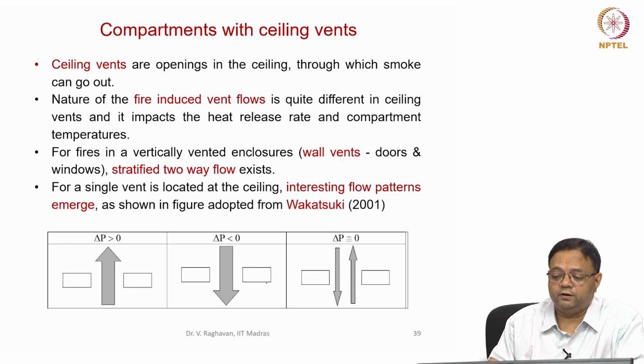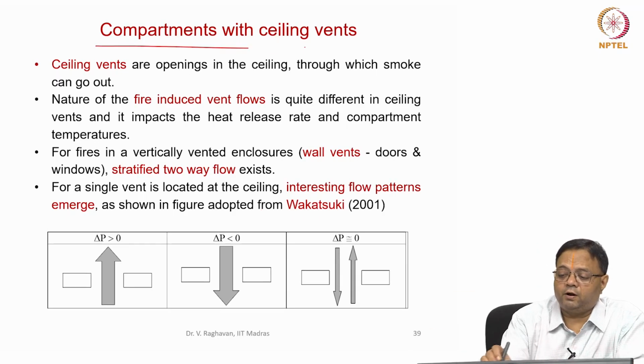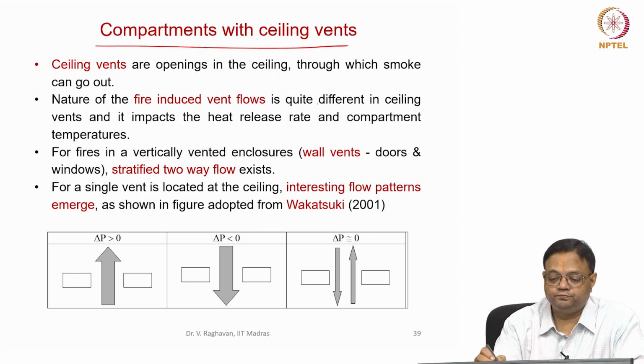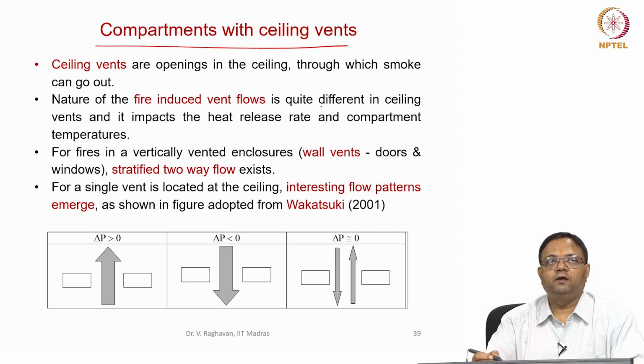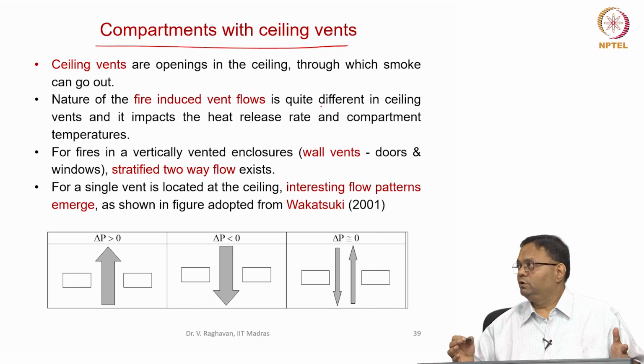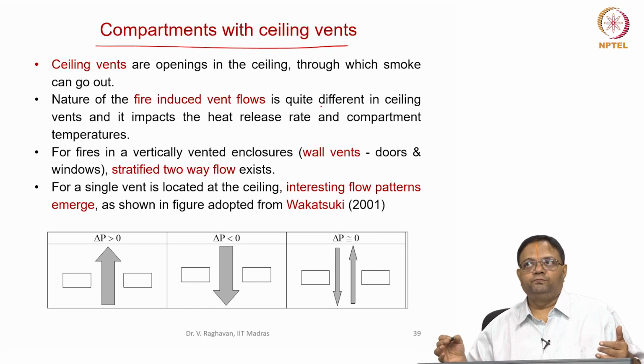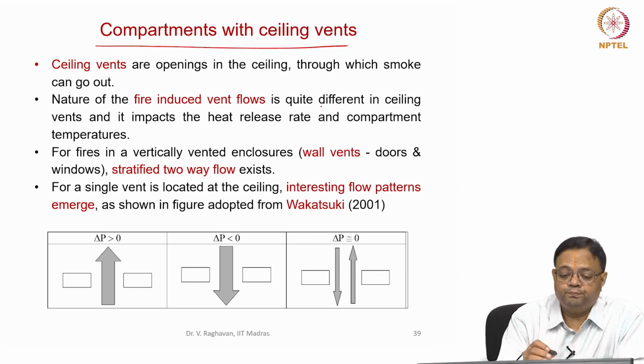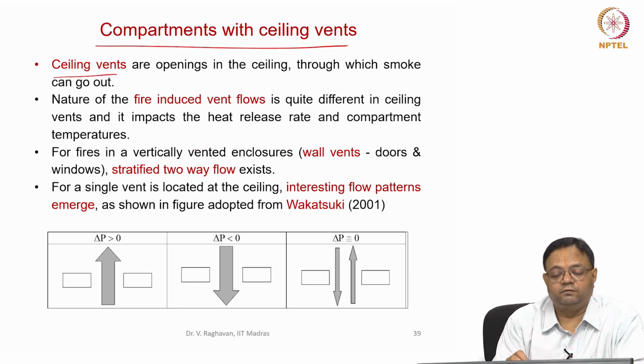Now let us see something where the compartments have ceiling vents. Normally vents are provided in side walls, where it can be in the form of a window or a door, etc. But in some cases ceiling vents can be provided, which are openings in the ceiling through which the smoke can go out.